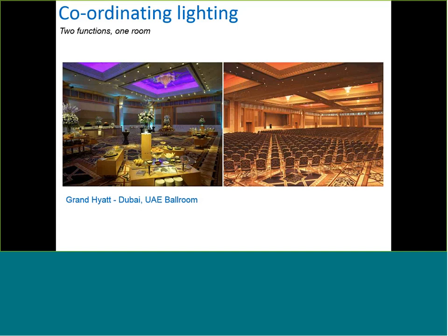With a network lighting control system, we're able to protect the design integrity to make sure that the scene that has been commissioned can be recalled at a single button press, and we're not dependent on the local staff to set 300 rotary pots to particular levels and make sure that we're able to recall the designed intent. This allows the system to focus on delivering the lighting scenes and the staff to focus on the guests.